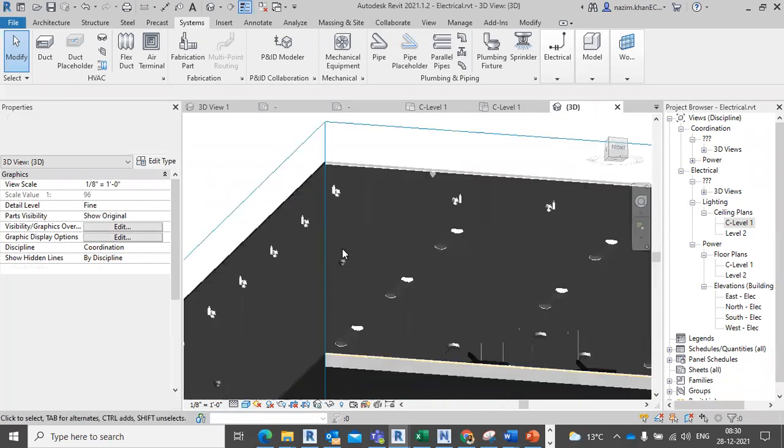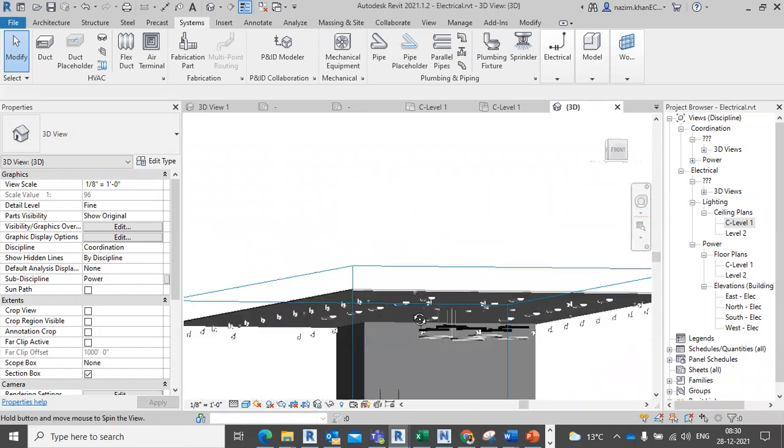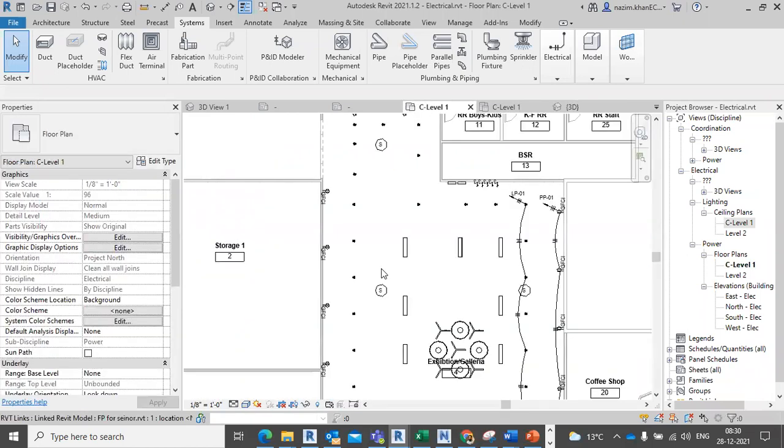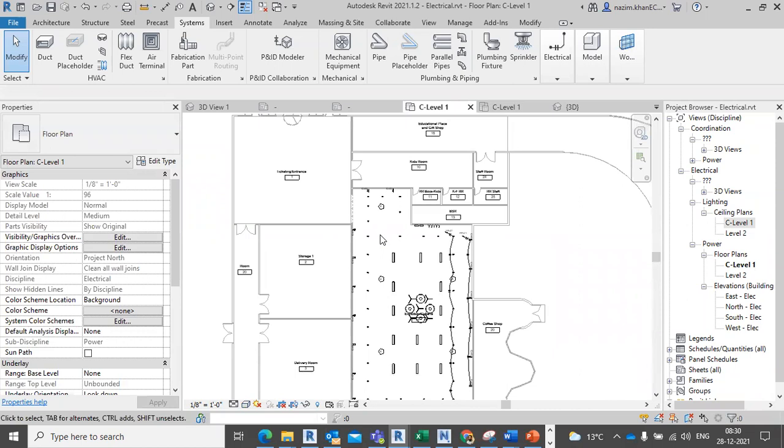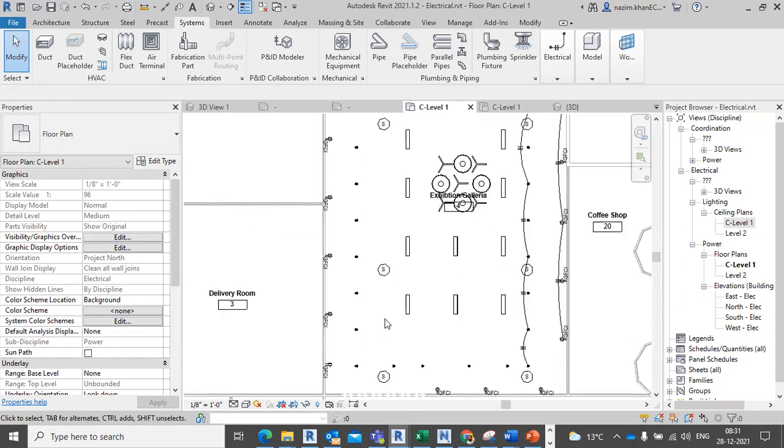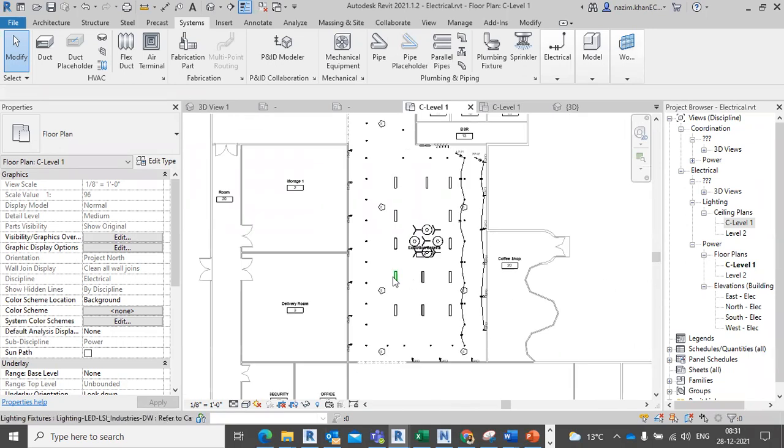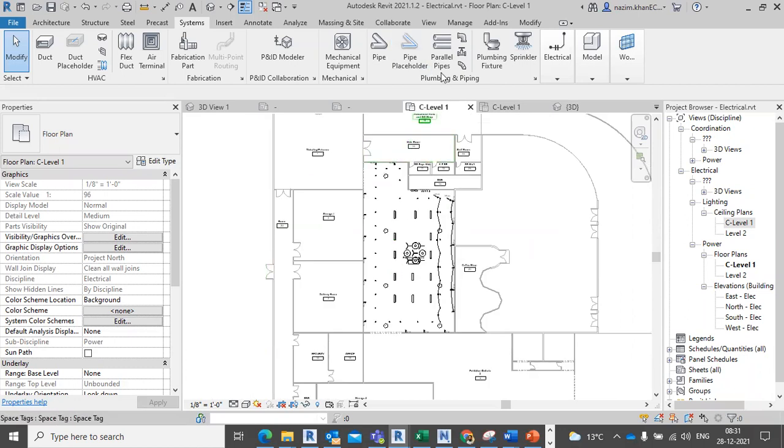So we have the fire alarm system. I mean, smoke detectors we have kept. Apart from that, we must have the speaker system also, because the entire fire system is divided into suppression, detection and annunciation. So we need to have at least one speaker in the premises, and that can be a ceiling mounted speaker.